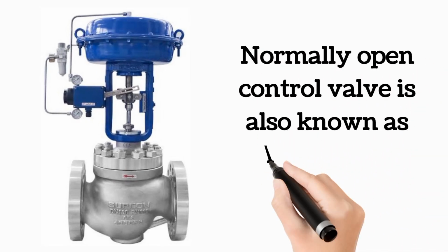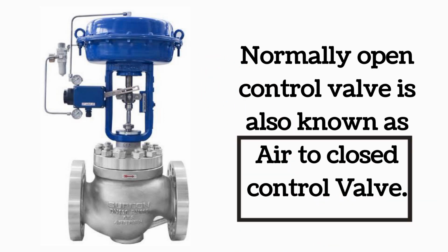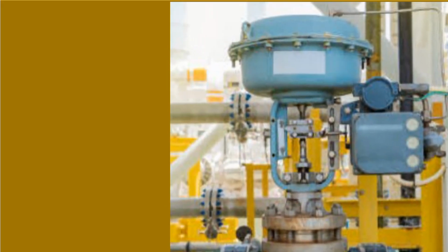Normally open control valve is also known as air to close control valve. Many people think that normally open control valve is air to open control valve. So don't be confused, why it is air to close control valve. Let me explain to you.